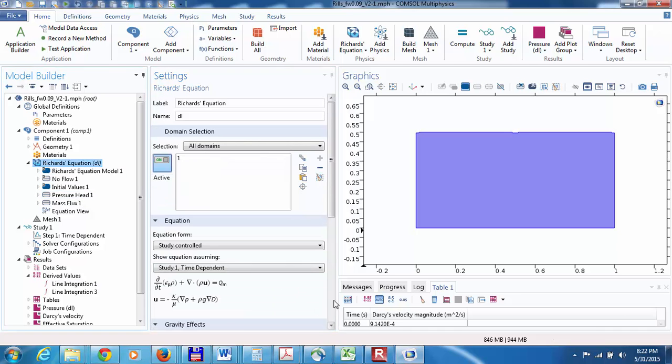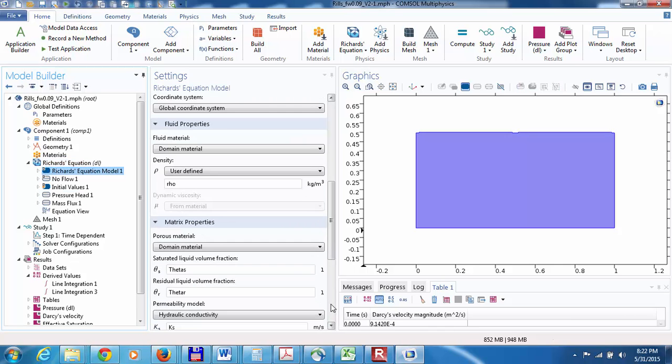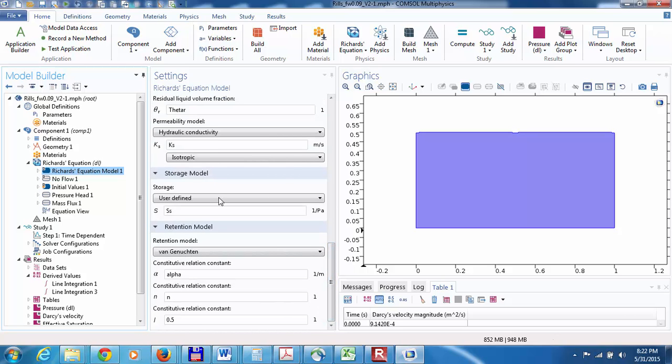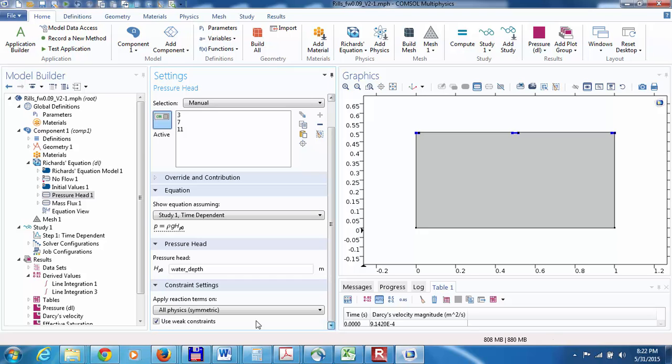So again, we've selected those boundary fluxes. I'm going to make sure that the Lagrange multiplier part is turned off, and that's under the specified head condition. And we see here that I've got it turned on right now, and that seems to cause a problem with the solution. I've just turned it off.